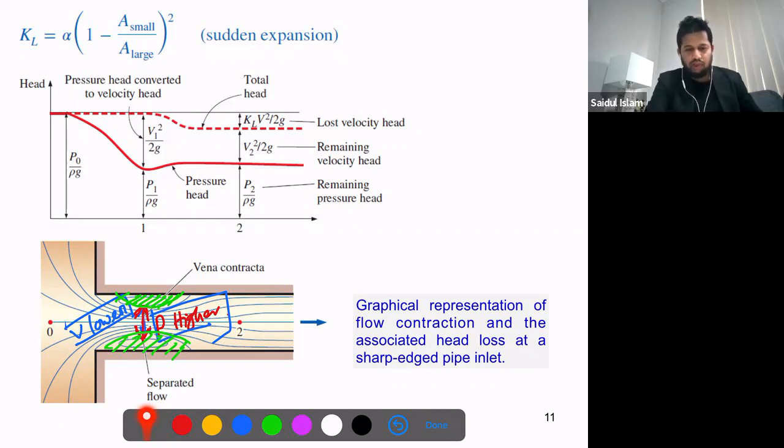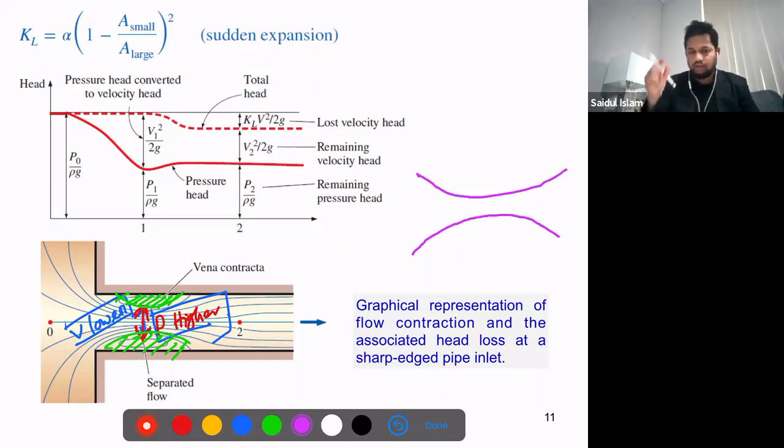If you don't want to speak, guys, you can write it down. What I said is not correct. In this section, the velocity will be higher because it's now a kind of narrow pipe. It becomes narrow. It's how the nozzle works. The nozzle outlet is very small, so the fluid velocity is significant over there. So in this section, the velocity will be higher and the pressure will be lower, because we know if velocity is higher, pressure is lower, and you can see that here.